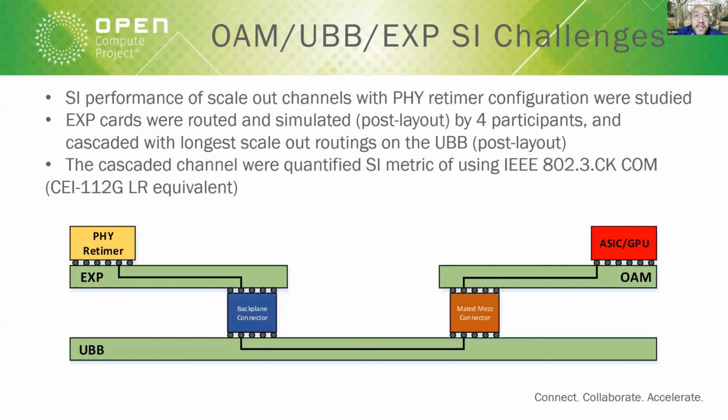They did the OD connector, as well as their routing on our standard stack up on the expansion card, routing to one of the major SerDes IP vendors on the retimer side. We terminated in the actual ball map, did the layout and did the post layout simulation.